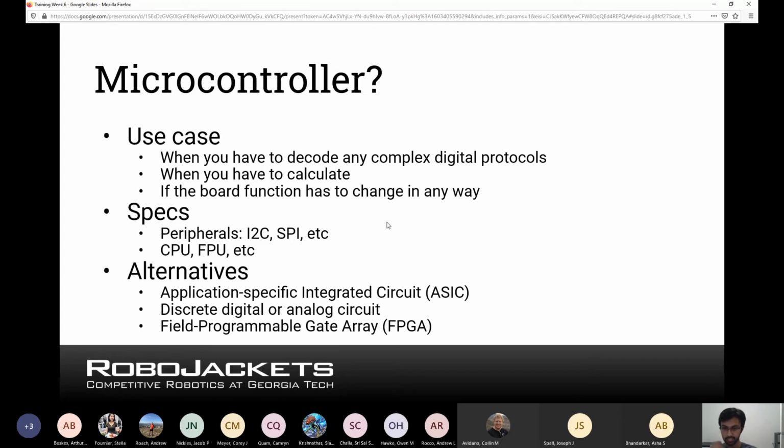So your block diagram might actually influence the choice of microcontroller here, because you'll realize, oh, I have this many devices that need to communicate over a particular communication protocol, which might motivate choosing a microcontroller which has more buses of that peripheral. So in addition to that, you might want to also consider just how well that processor performs.